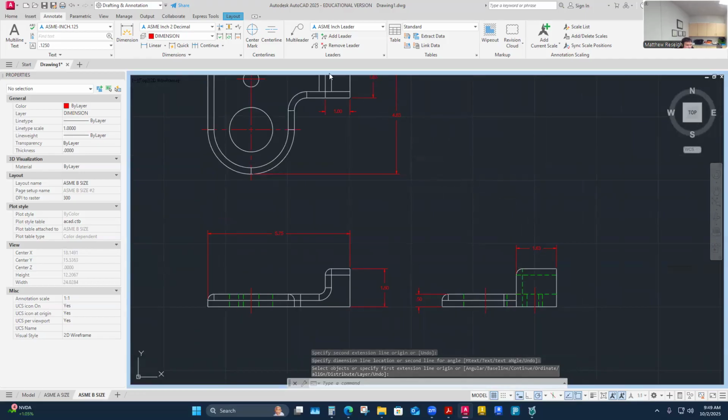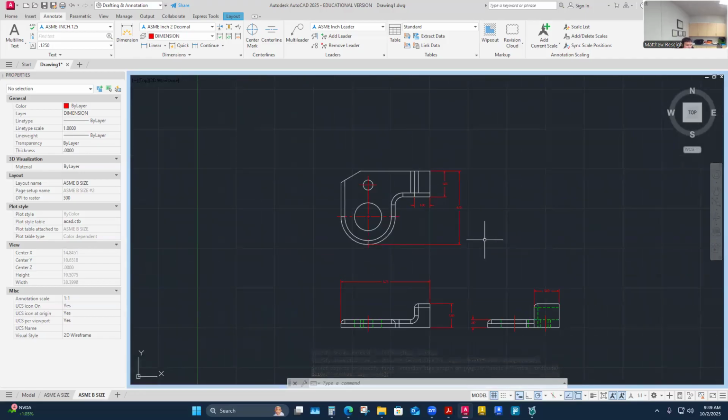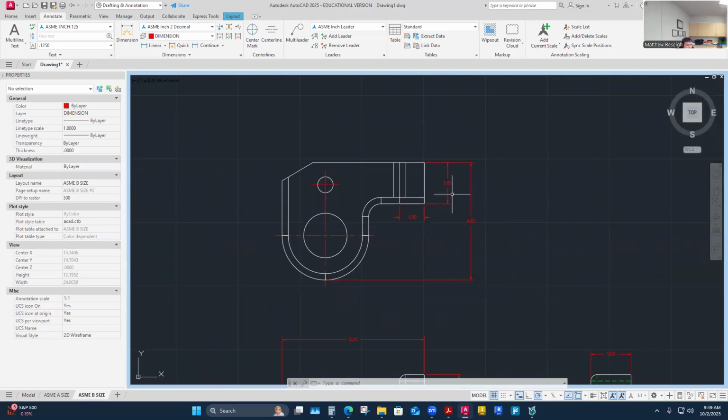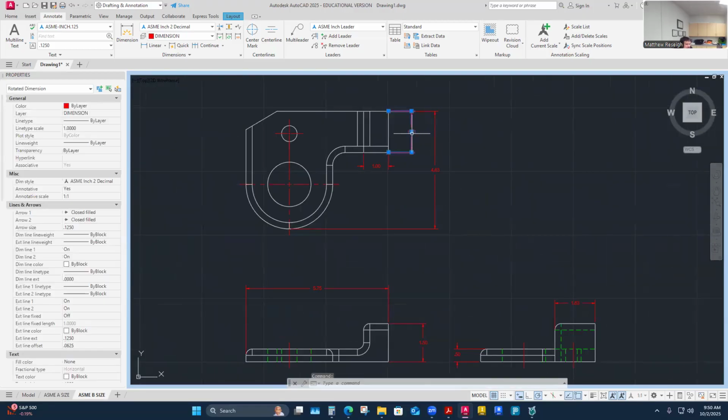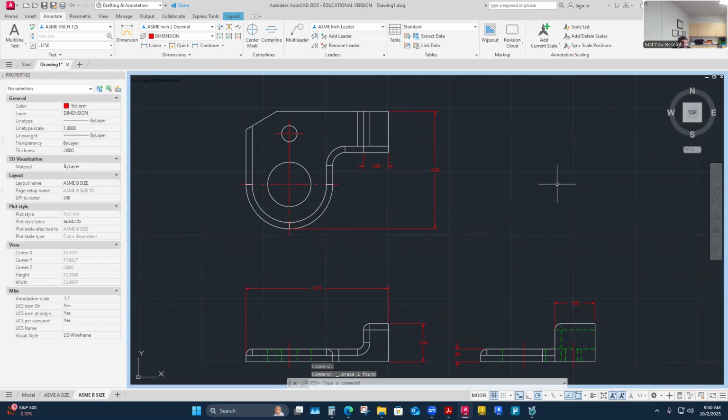I wouldn't care which one you chose because to me they're pulling from the same point. So either is good. I just wouldn't want both. That would be dual dimensioning, double dimensioning. It's the same dimension. I know it's two different views, but it's the exact same dimension. So you just get to pick one or the other. Maybe I'll just, for no other reason, delete that one. But I may come back and put it in, if I decide that's where I want it.